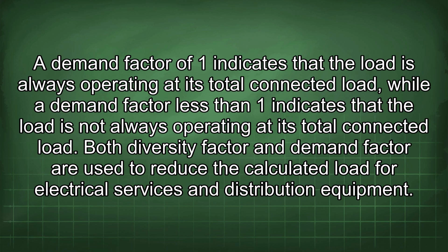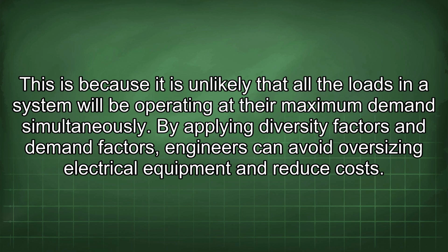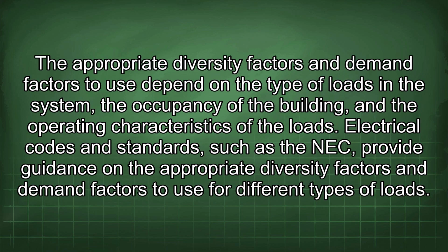Both diversity factor and demand factor are used to reduce the calculated load for electrical services and distribution equipment. This is because it is unlikely that all the loads in a system will be operating at their maximum demand simultaneously. By applying diversity factors and demand factors, engineers can avoid oversizing electrical equipment and reduce costs. The appropriate diversity factors and demand factors to use depend on the type of loads in the system, the occupancy of the building, and the operating characteristics of the loads.